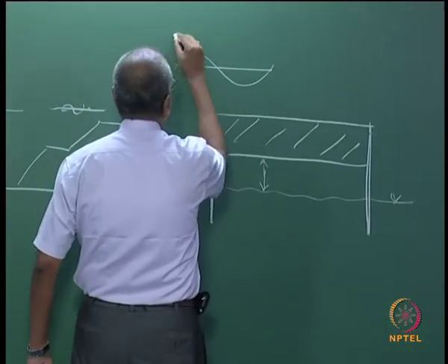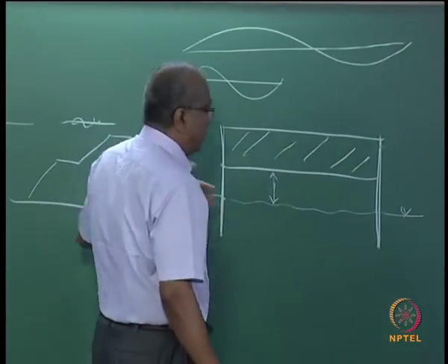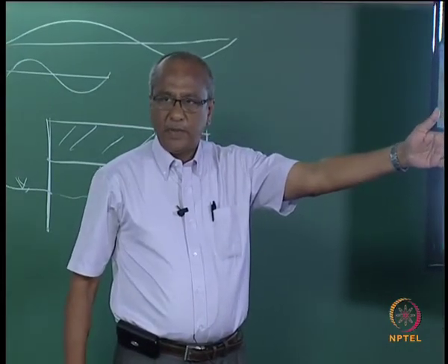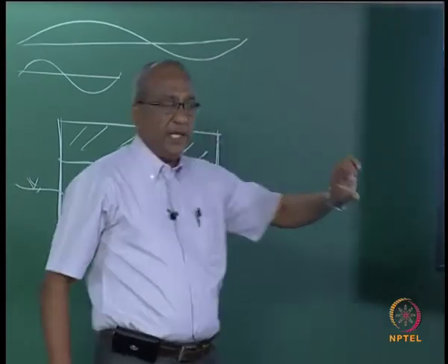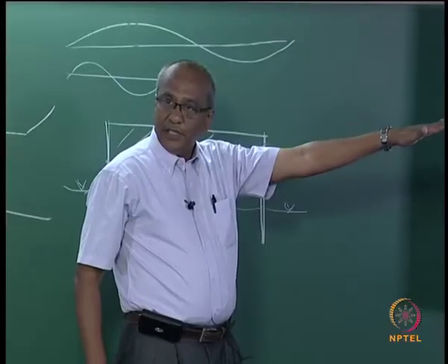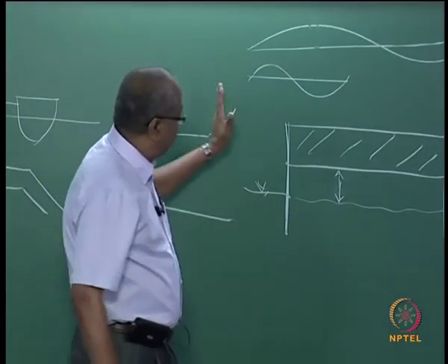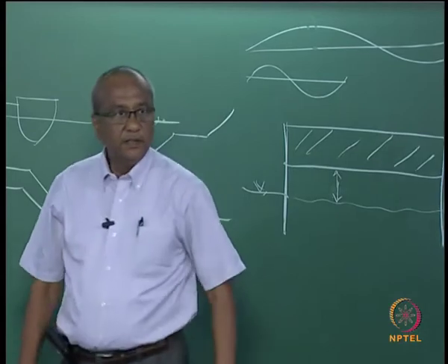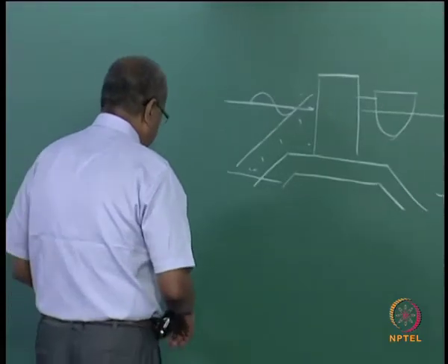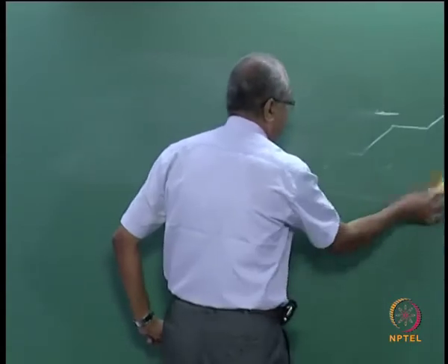Why do I say that? So for example, if you have a long period wave, this will easily penetrate through under the skirt without the amplitude getting attenuated, it can simply move. Understand? Whereas if the period is short, it can get attenuated when it is hitting the structure. You understand? These are all some of the considerations which you need to take into account when you are planning for any kind of a breakwater.